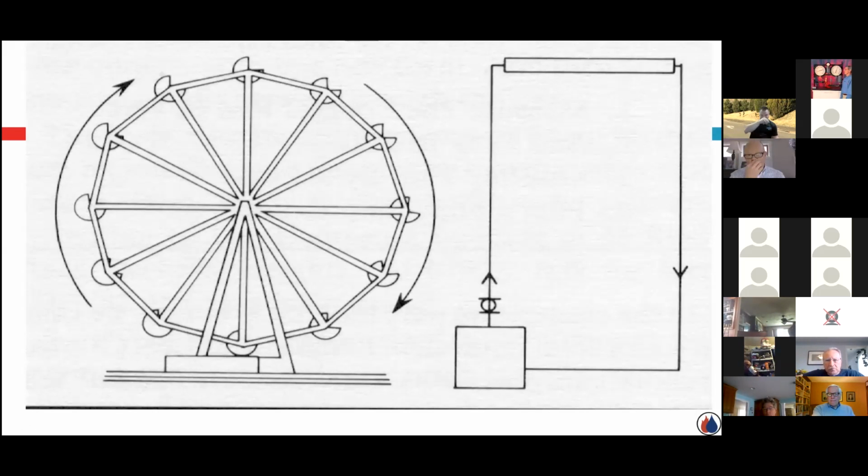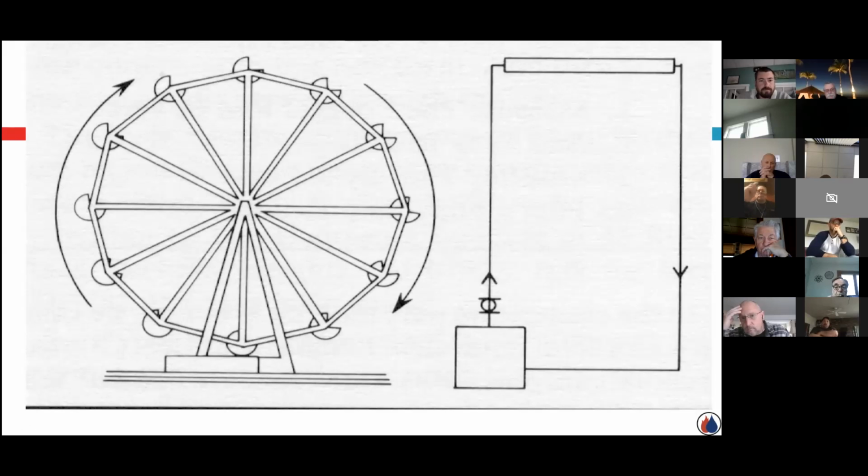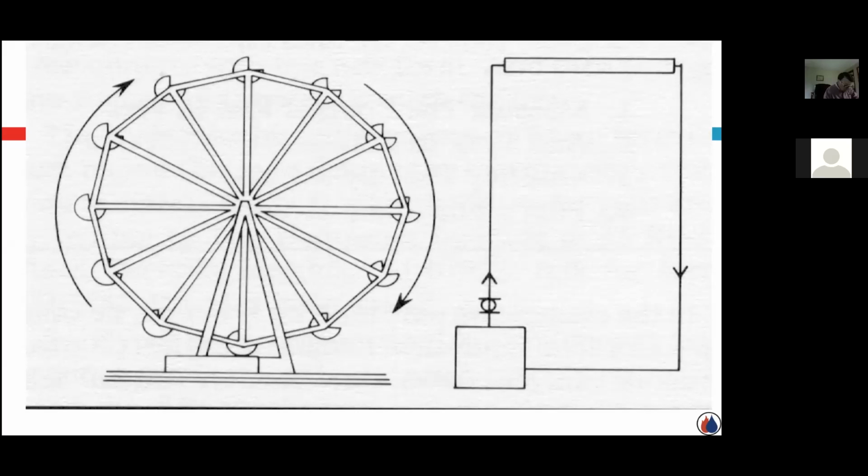The point of this picture here is to just try to remove any misnomer, or whatever theory, a thought, I should say, not theory. The job of the circulator, like we just talked about, is to move the water throughout the hydronic system, be it chilled water, hot water, both, whatever the case may be. Over the years, I've had conversations where someone will call me, and somehow it'll become, hey, I think I need a high-head pump. Okay, well, why? He goes, well, I'm in downtown Boston, and I've got this 5-story brownstone, and I've got to get the water from the basement all the way up to the highest piece of baseboard in a cast iron radiator on the top floor.